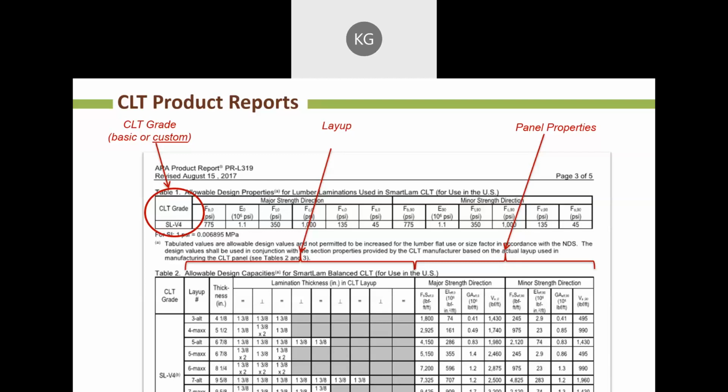If you've designed those before, the most efficient way to do this is to engage the manufacturer during the design phase. And that way you can tailor your design to their strength values, their manufacturing capabilities, and usually they've got an engineer or engineers on board that can help make the project efficient, help design the panels and the connections, and that kind of thing.